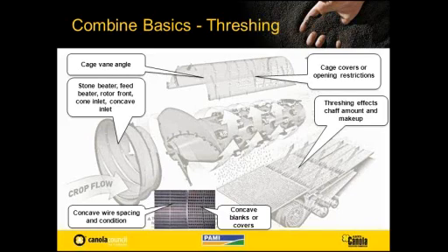These concaves are often blanked, sometimes just to move material around, but sometimes to keep the crop in there and allow more impacts without necessarily having to increase the frequency due to rotor or cylinder speed.